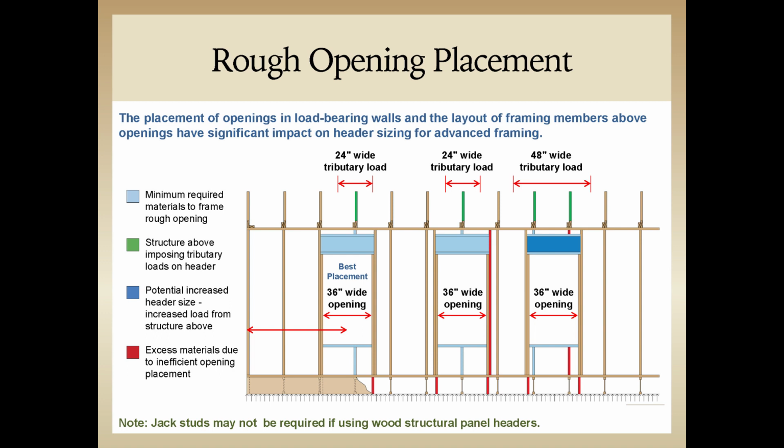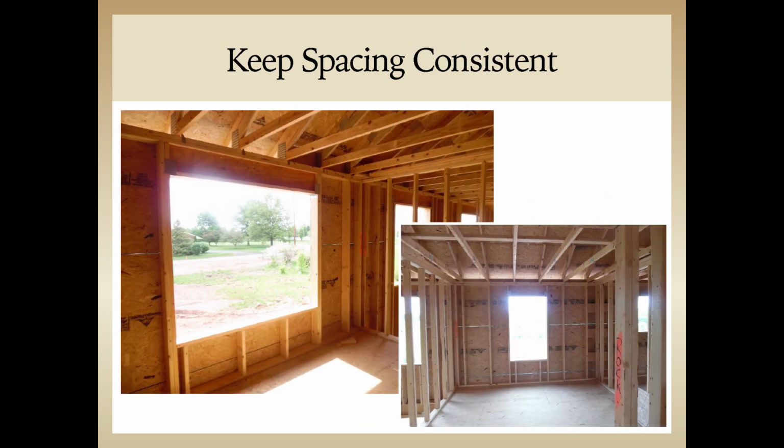If your design allows your windows to be placed at 24-inch spacing, it helps not only with the optimization of lumber, but also with other trades being more efficient with time and materials, such as having full width bays for insulation. And we know it's not possible for all windows and doors to be placed at a 24-inch module. So when that number can't be hit, builders who have already implemented advanced framing have found the easiest way to frame. So the area of these walls I want you to focus on is the cripple studs under the windows.